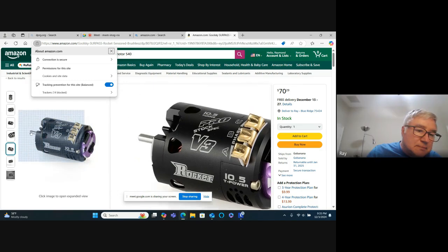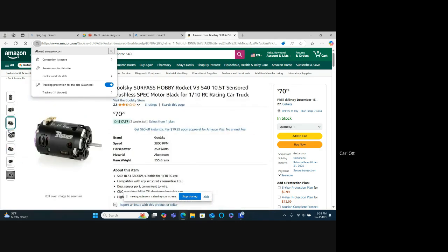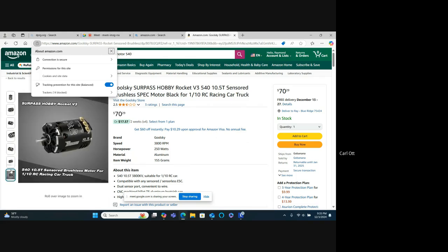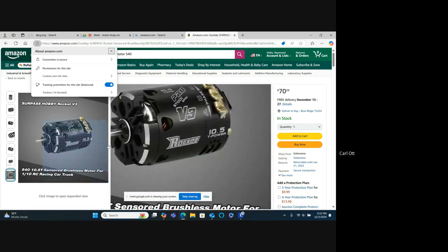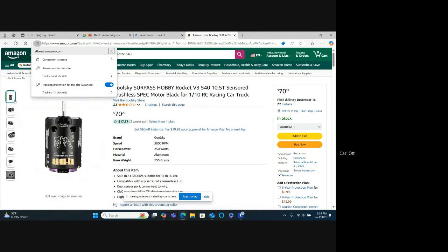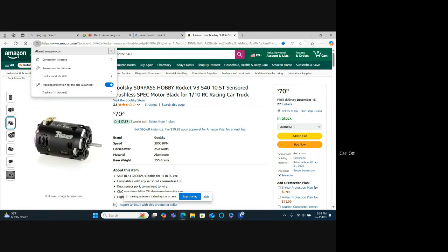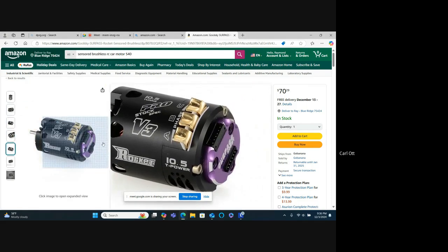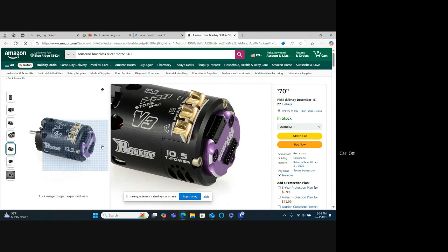Oh, okay. The first thought that came to my mind, until Kareem told me I could get this super duper high-end controller that measures torque and washes your windows and everything, was that I would use a regular old boring sensored RC controller that doesn't have that fancy stuff. And then I would use the second connector, without having to have a splitter cable, and run that off to whatever controller board, Arduino or whatever, and count encoder ticks without having to hack into the controller.